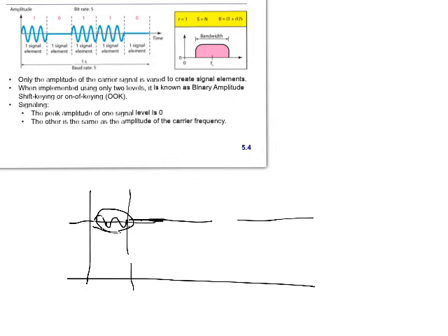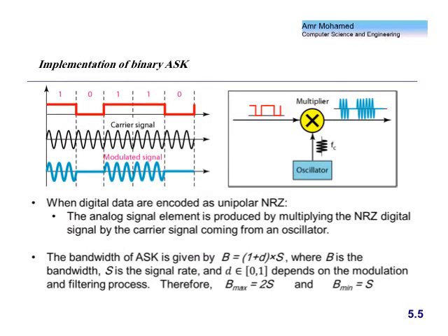But in any case, in normal conditions, attenuation affects the on-off keying drastically. Okay? So it's easy to affect the amplitude more than the other two types of characteristics, which are frequency and phase, as we will see. So the motivation behind using another characteristic is that the amplitude of the signal seems to be very prone to noise. So again, the implementation of on-off keying is very easy.